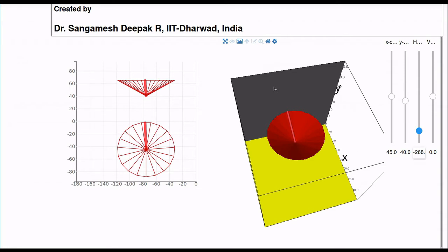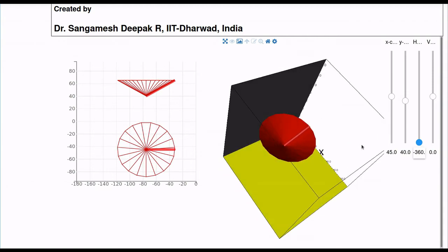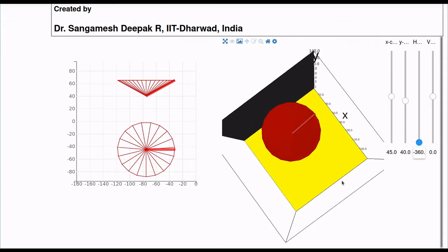Okay, so that is it. So as I said, whenever we say that there is an inclination, especially of a line with HP, you of course start by taking a line in a configuration where the line is parallel to VP, and then you also recognize that you can also rotate it.